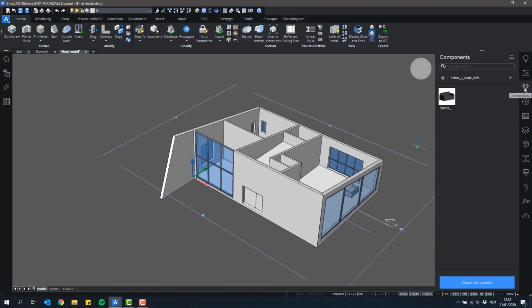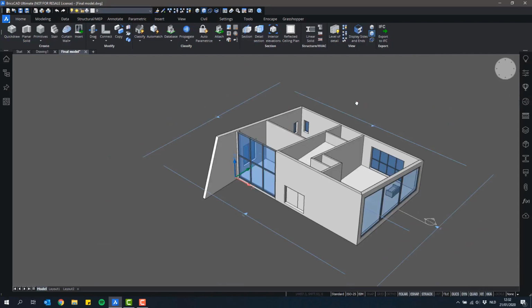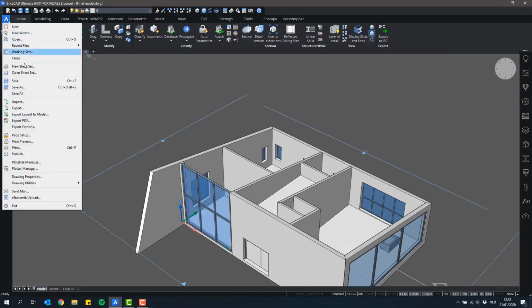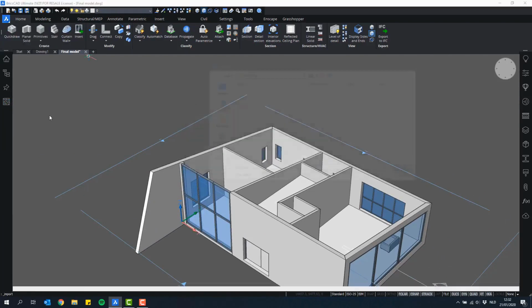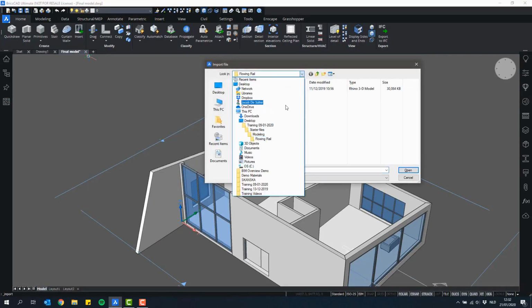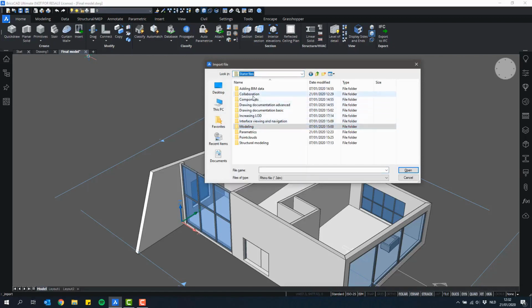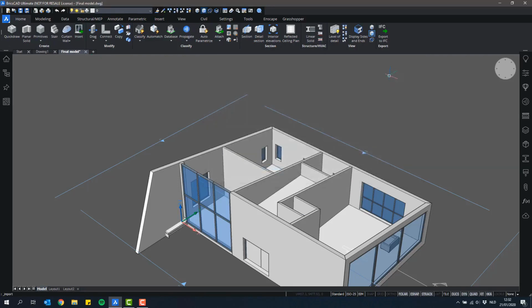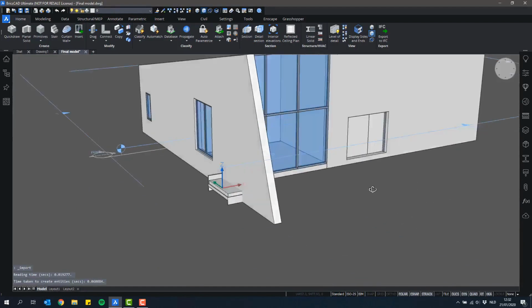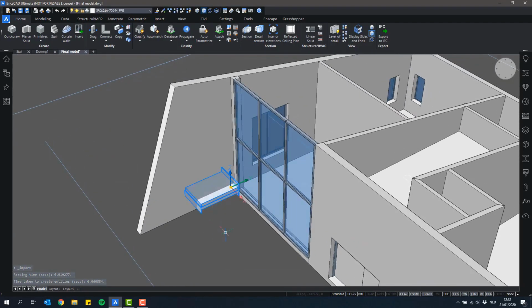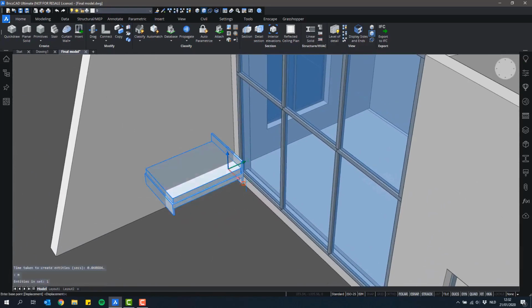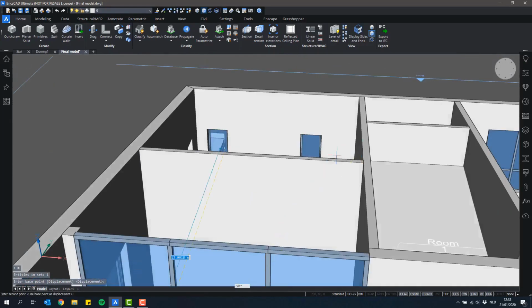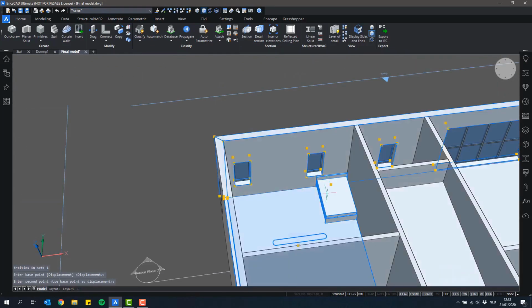It's also possible to import IFC files. For this, we'll have to use the Import tool. So I'll click Import and go to the collaboration folder. There's this NBS folder that should contain an IFC file, just of a component. Now when we insert it or import it, it will be automatically imported at the origin. So we still have to replace it manually. Like this, for instance.